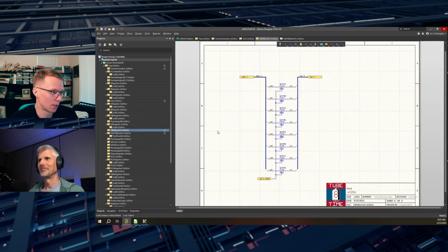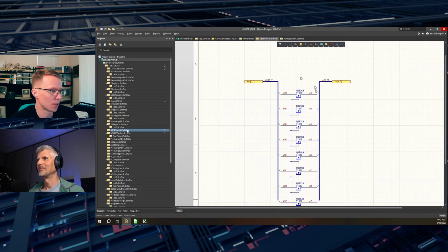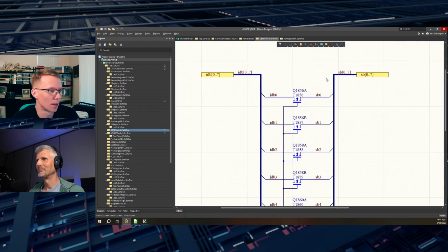So this right here is one of the bus switches I was talking about. This actually connects 2 different internal buses together. There's a very similar circuit that's used to connect individual registers to a bus. And basically what we have here is an array of transistors that don't really have a source and drain. They have a substrate connection that's not tied to either channel connection. It's simply connected to the substrate.